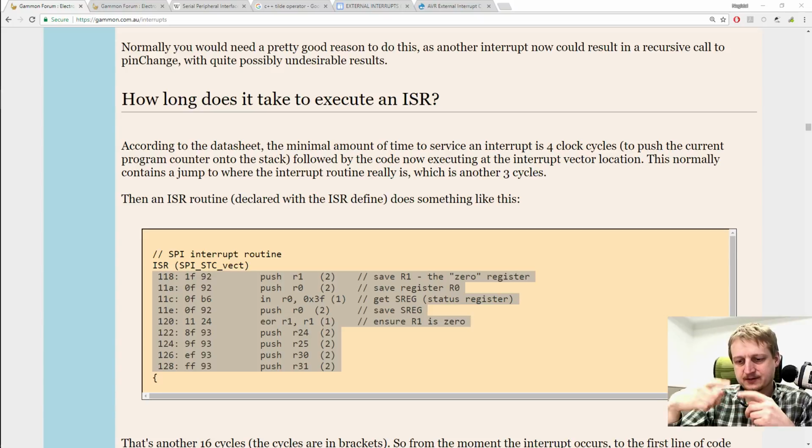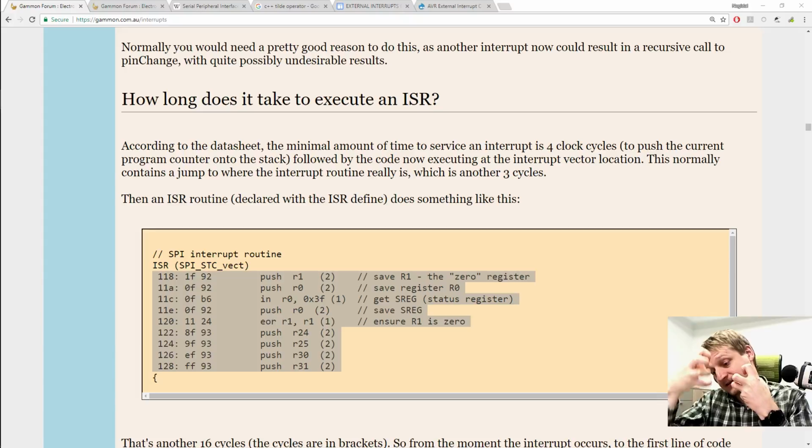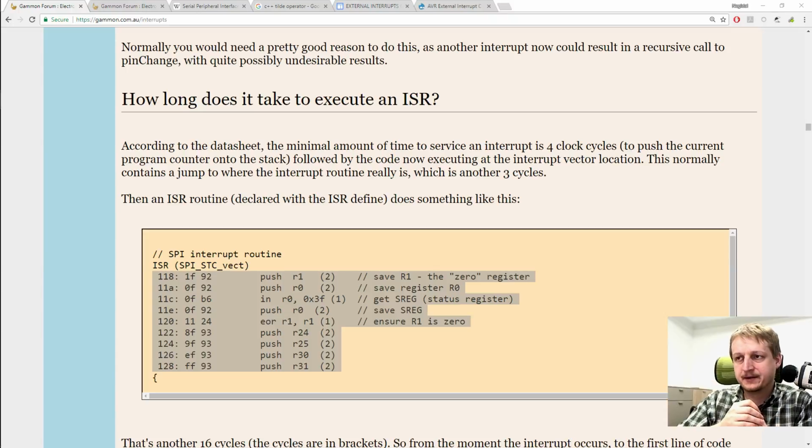The motor has to translate to a slower rotation, which also has more torque than the fast rotation of the DC motor. And I need to find a suitable translation ratio. But for that, I need to first know how fast the motor rotates and roughly how fast I want my axle to rotate, and then I can figure out the transmission ratio. So this is all relevant to the Arduino Tapper project.